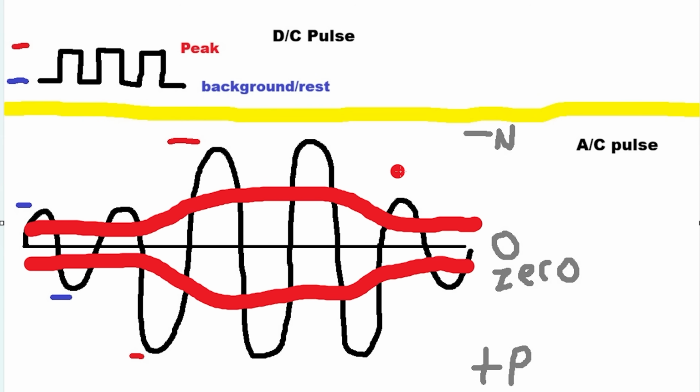Pulse on AC tends to be something I don't recommend to people, and the reason's simple. If you remember in the first lesson in this series, I talked about hot shortness sensitivity of aluminum. Well, guess what? If you were to set your pulse at 200 amps and your background current down here at like 40 amps, what would actually happen is you would induce hot shortness cracking into the material, because you're bringing it up super hot, super fast, and then killing the heat, allowing it to cool very fast. And once that molten puddle were to dry up, you'd more or less have instantaneous cracks in it. So doing pulse on aluminum, I generally don't recommend it.